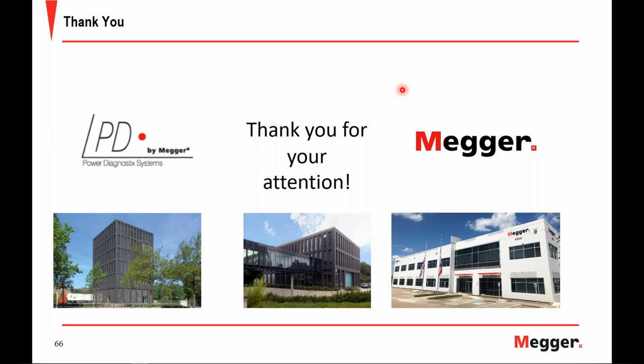So the setups are identical or very similar, but the equipment is slightly different in what you use. As far as software, the ICM system is capable of in-depth analysis, as we saw. It's a parallel channel instrument, so you have a simultaneous updated multi-channel panel. And with the ICMflex, you're capable of performing your tan delta and capacitive measurements, as well as your partial discharge at the same time. So that gives you a benefit of performing those two there. So there are some differences there.